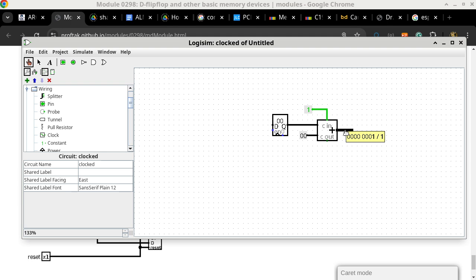In other words, right now, the circuit is taking the output of the register, which is 0, taking the second input to the adder, which is also 0, taking the carry in, which is K0 in the discussion that we have about the adder, adding all three together, and this is the output, which is a 1.